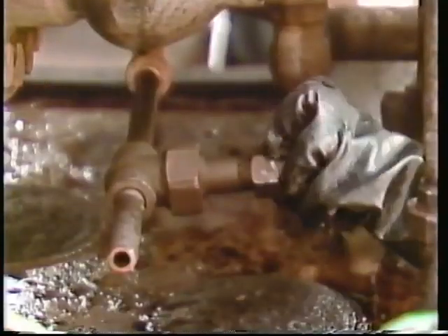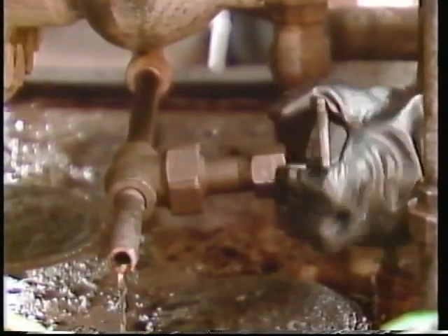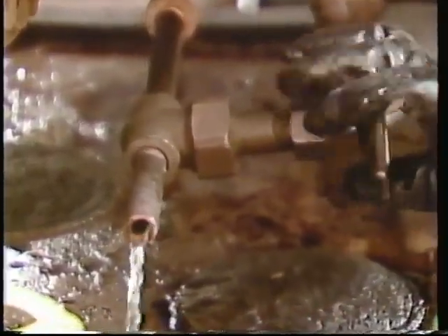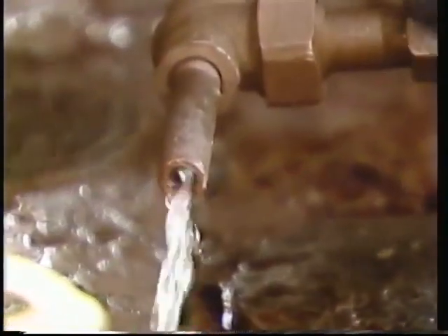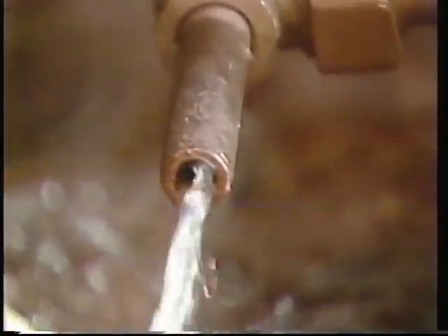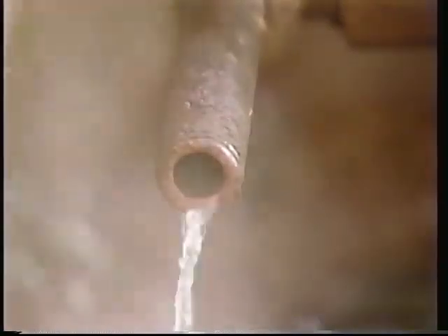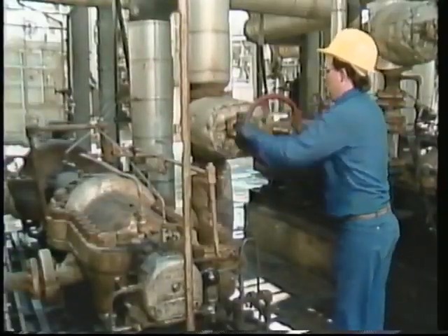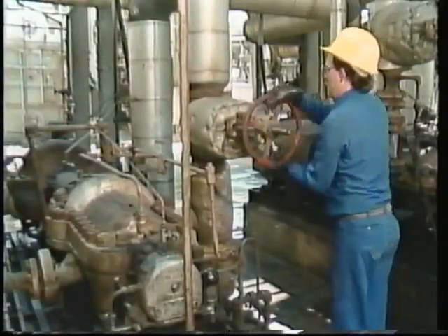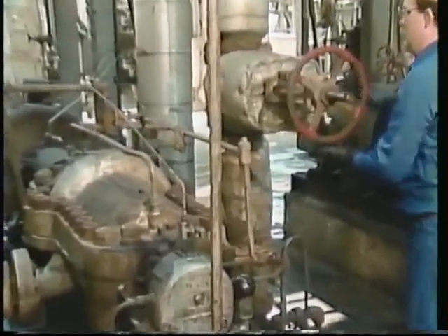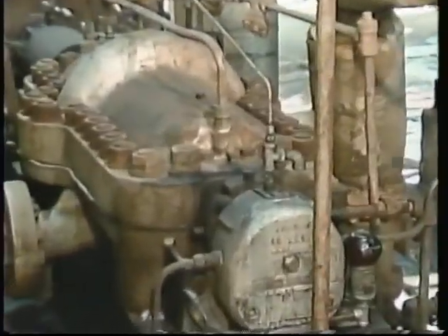You'll need to check the exact procedures required for the turbines in your facility. After the auxiliaries have been attended to, the operator opens the drains for the casing. This helps prevent water from collecting in the turbine. Finally, you'll need to perform whatever shutdown steps are required for the equipment that is driven by the turbine you're working with.